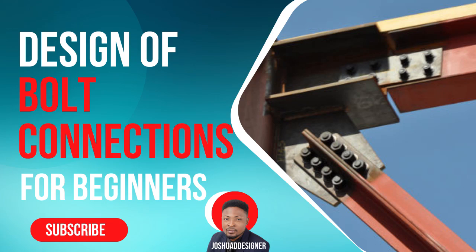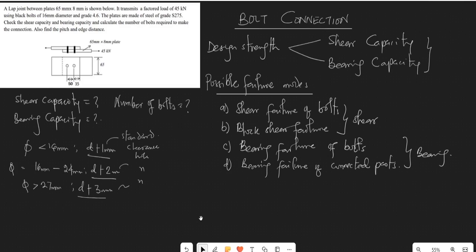All right, so if we are going to start with what you have already declared, we are going to say that for the bolt diameter given here, black bolt of 16 diameter, the standard clearance hole, which we could denote as capital D, would be small d plus 2, based on what we saw in the code. So that is the first consideration from the question, plus 2. So we have 18 as the standard clearance hole. I believe that's clear enough. Now from the question, we know d is 16, so we have no trouble on that.